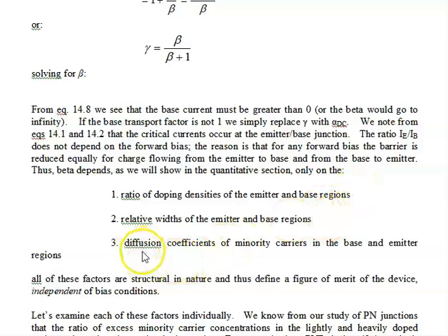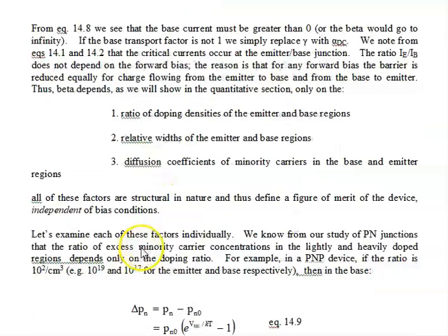And the diffusion constant depends basically on whether it's an NPN or PNP. The NPN always will have larger diffusion constants, so NPNs are a little bit more efficient. But here we're not even talking about factors of 2 or 3. We're generally talking about factors of 30 or 40%. So this goes from the biggest to the less and to the least.